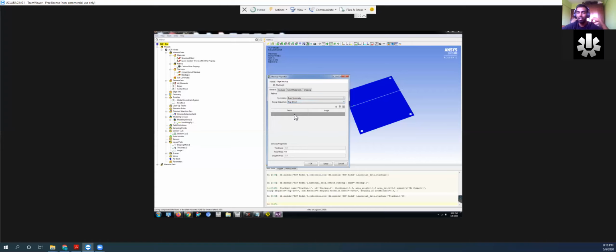So, for example, if you have a wing and you want it to deflect in an opposite direction, or you want it to twist when there's a loading applied normally to it, so that the angle of attack increases or something like that, you can do it with different material properties, with the different ply stackups. But for now, we're just going to keep things simple. Generally, things like the seat and the steering wheel will all be done with even symmetry, where we're not talking about any crazy material properties that we want yet. But if you take an advanced mechanical engineering class like MAE 166C, you'll see what I'm talking about and how to achieve these different types of material properties.